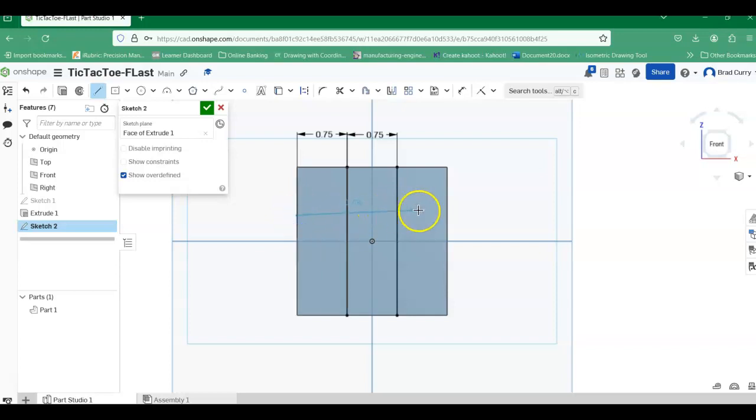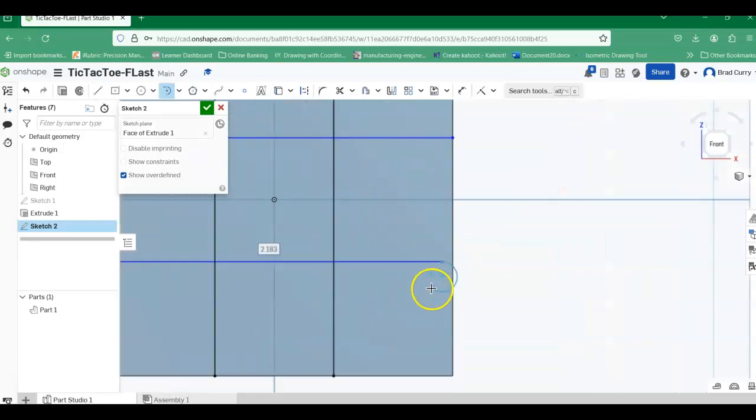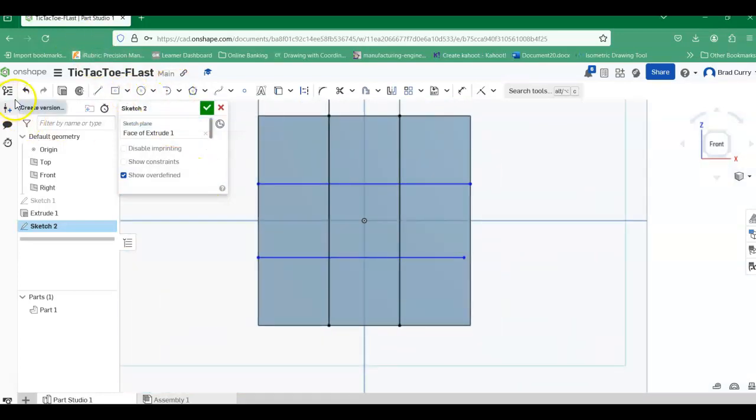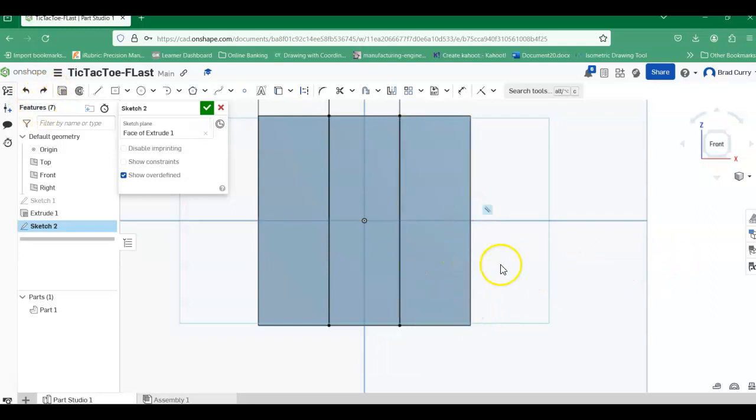Now, I'm going to draw some additional lines here too. So we're going to do a horizontal line from there, so I'm left clicking on that line. Notice how it's locking in and putting a constraint there, which is what we want in this case. We want this locked in at the horizontal, and we want it to be locked into that edge there as well. So I'll left click to place that, right click, escape, go back to my line tool. Again, I'm going to left click on the edge, make sure that it's giving me that funky looking line to constrain it horizontally, left click to place it. Now, notice this is where we have to be careful because it didn't go all the way over to there. So let's escape that. I'm going to undo that line. This is our undo button. Notice there's a little delay, so sometimes you have to have a little bit more patience. I was moving a little too fast right there, so let's go back to the redo. So that places that one in.